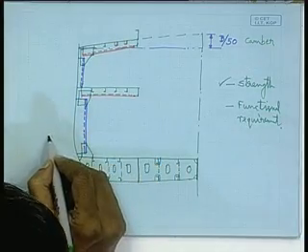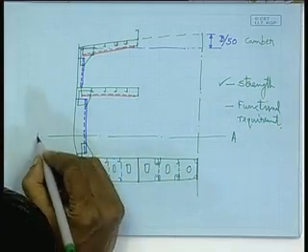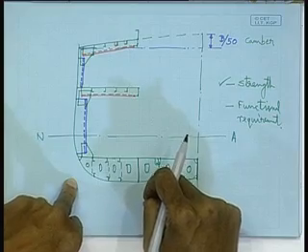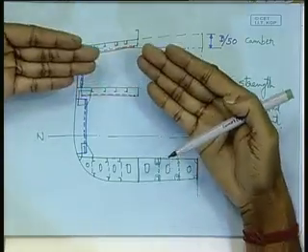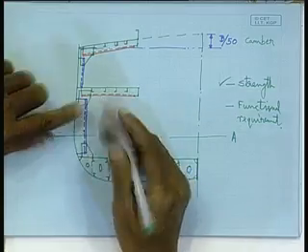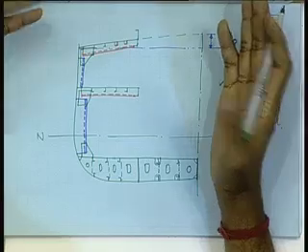That calculation essentially involves finding out the neutral axis of the section. Obviously, while doing the calculation I will take the full section, because the whole section will contribute towards the strength. So, finding out the neutral axis and finding out the section modulus of this. How do we get that? Well, we take only those longitudinal members. Obviously, the deck transverse and side shell frames will not contribute. Naturally, they are not contributing towards longitudinal strength. So, their section modulus does not come into the picture, right.